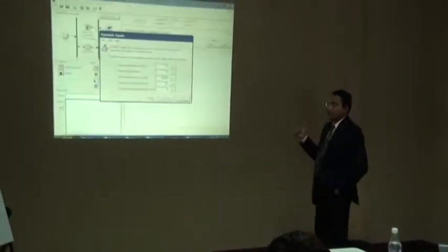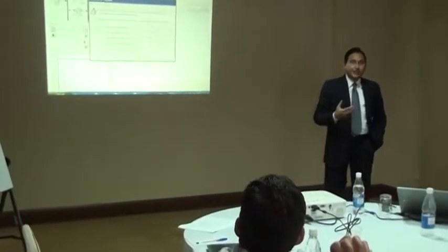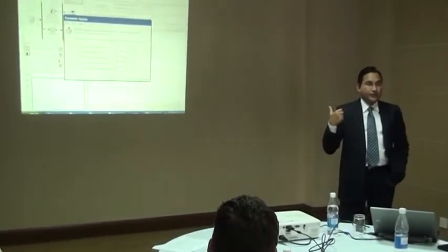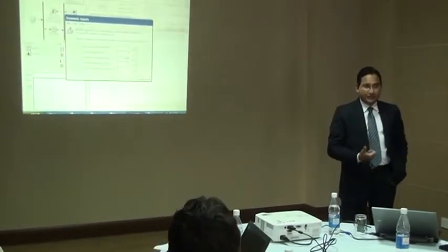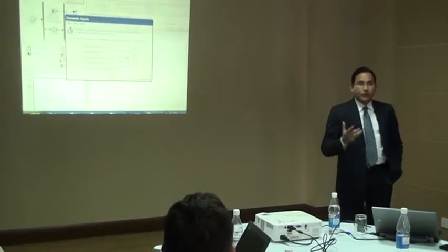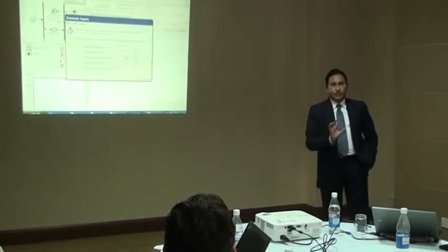Yeah. The fixed O&M cost per year. Now, remember, we haven't taken the O&M cost for individual components like battery, PVs, rectifier. We haven't taken any individual O&M cost. We put a 0 while doing the configuration. But we have taken an O&M cost only for the DG, the diesel genset, of $0.50 per run hour. So we have to take all the O&M costs of other equipment. Let's consider it as a package cost.